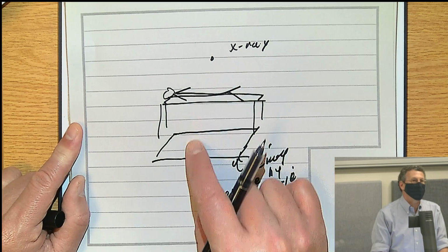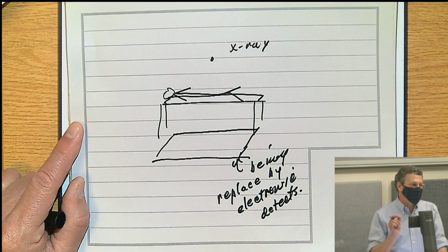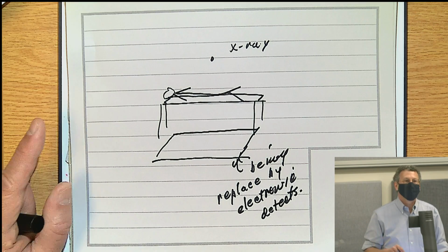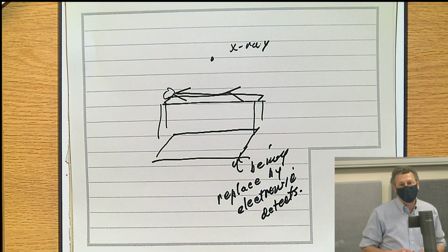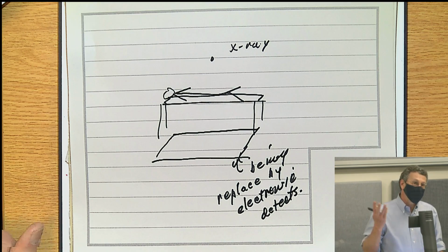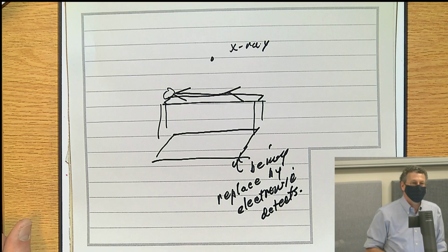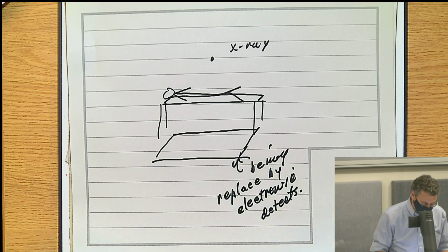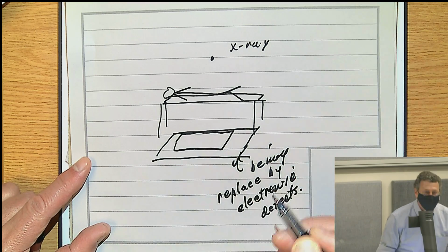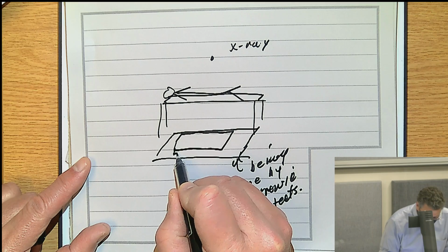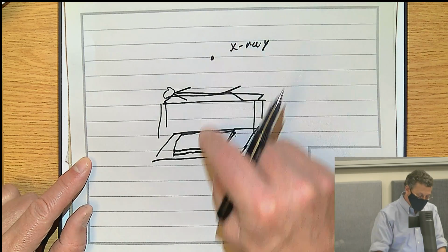And X-rays typically can't be detected directly by electronic devices because they will just go right through the detector. So if you have a silicon device like a CCD, it would detect visible photons, great, but not so much X-ray photons. So they have to have what's called a scintillating device in front of it. I'll talk about this some more. It's basically a crystal of some material that is dense to the X-rays and stops the X-rays, otherwise they'll just pass right through.